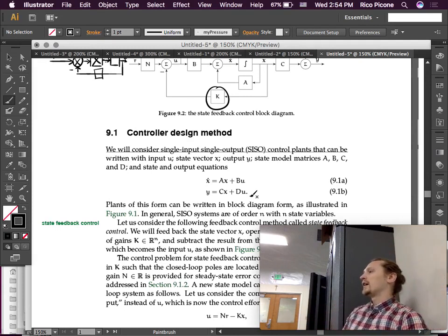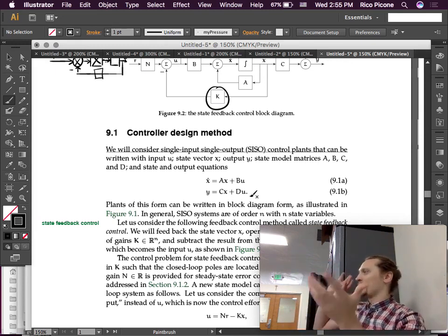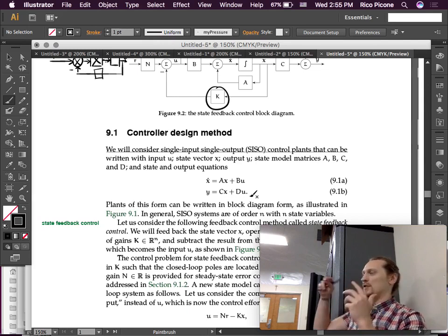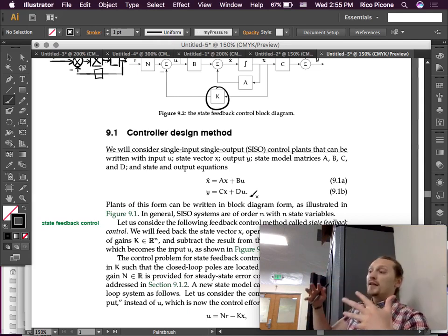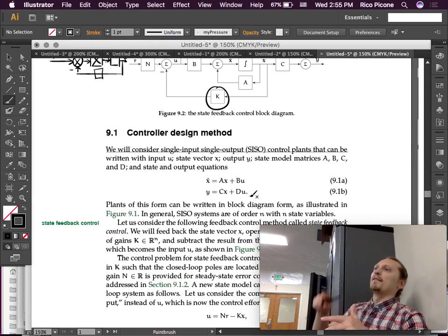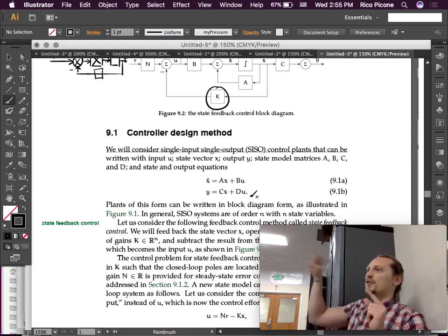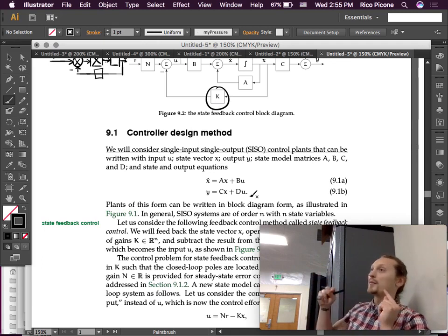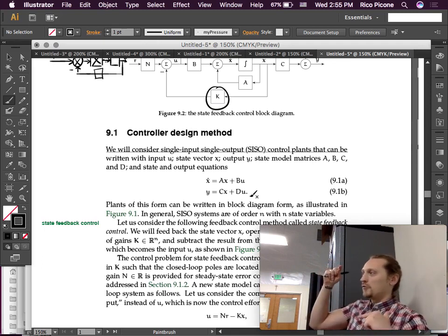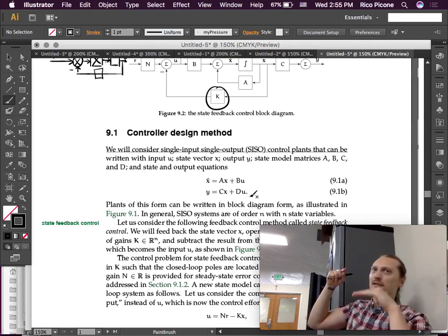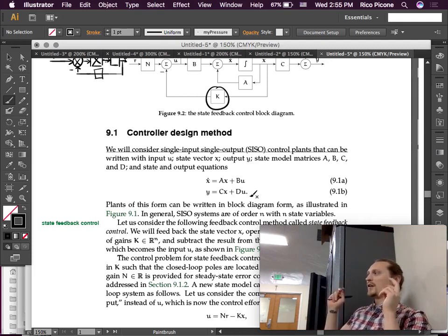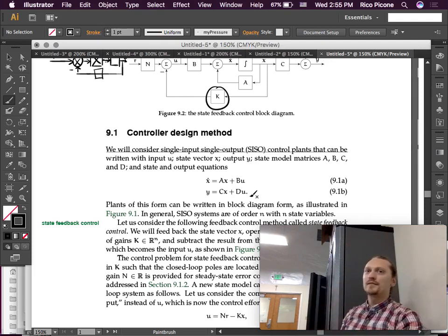It's just like in our project where the motor voltage is the input to that electromechanical system. That's the voltage that drives the whole system. But we want to do control. We don't want to set that voltage. What we want to do is set the position of something. So our command is going to be a position, and the voltage is going to be whatever the controller says it's going to be. And so our new input to the system is our command value. Same here.